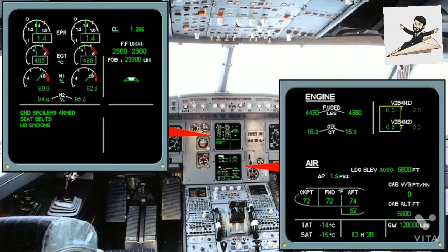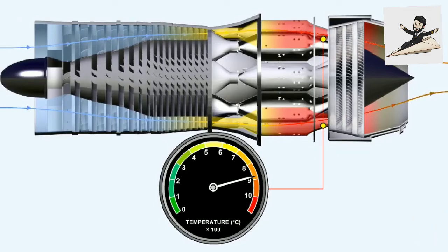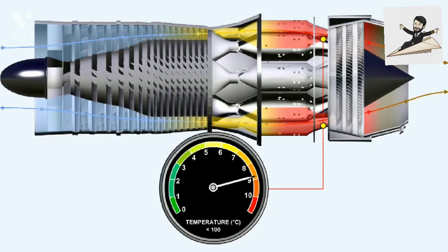An increase in the vibration level of the engine, which can generate noise, which may become audible in the cockpit, depending on whether the engines are wing-mounted or rear fuselage-mounted. And an increase in the exhaust gas temperature, otherwise known as EGT. This latter effect is caused by the fact that there is less air going to the combustion chambers. Hence, there is less air to cool the products of combustion, the exhaust gases.